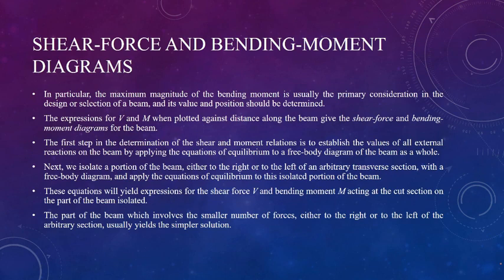You have to understand one more important point. Once you have developed a free body diagram, established all the forces on the beam, develop all the equations, that is equilibrium equations of the beam, then you have to understand, once you open for a shear force, that shear force act in pairs. This means the conventions you have choose from one side, equal and opposite is going to go through the next side.